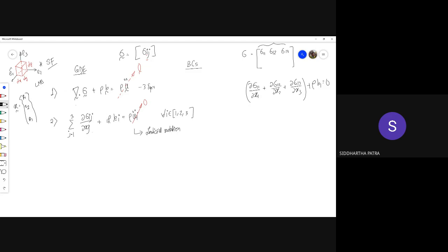And let's now talk about the boundary conditions. So u is given to you as u bar in gamma u. Basically, you know the value of u in gamma u, and t may be given as t bar in gamma t, which means that sigma n in gamma t, sigma times the normal, the usual Cauchy equation, equals t bar.